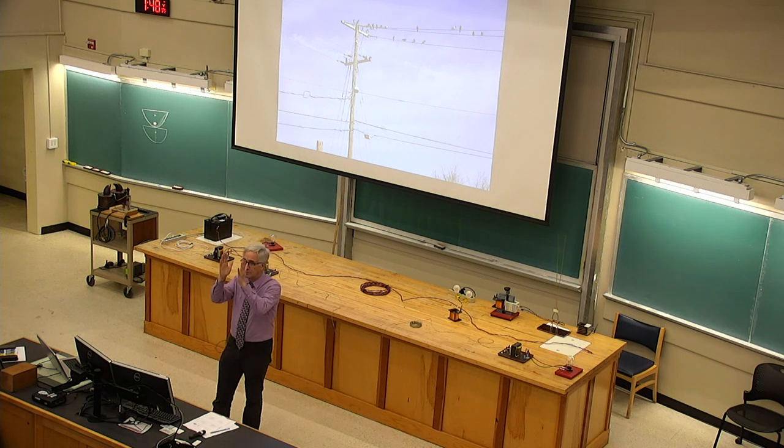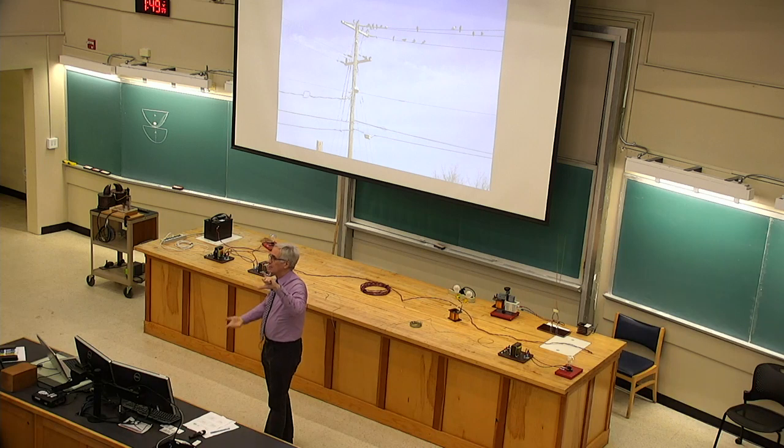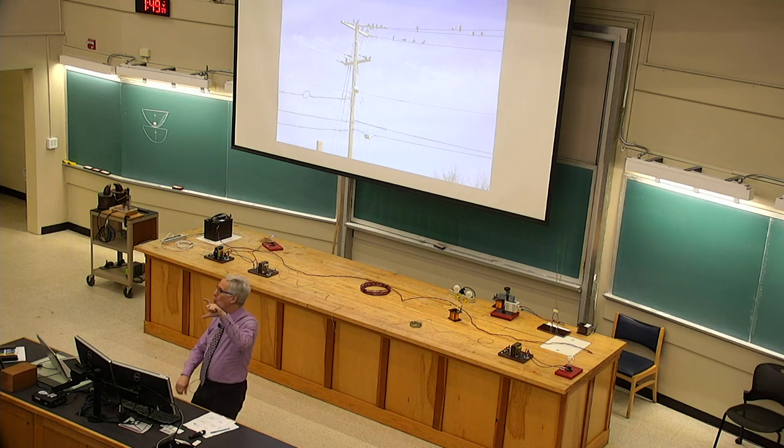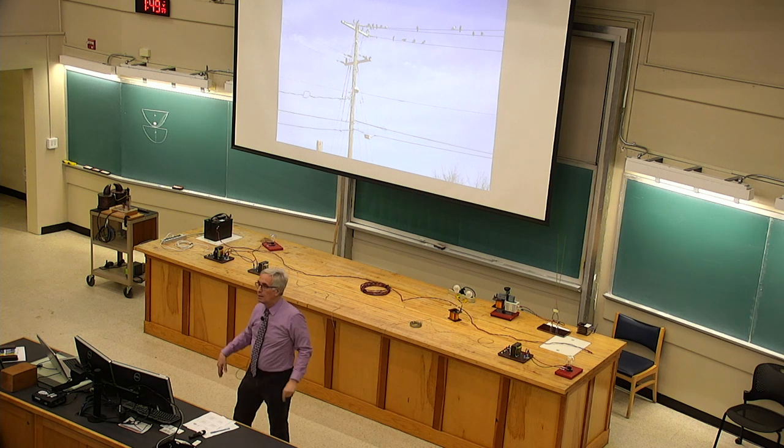The 2 slots. And the way they've got it arranged, standard electrical power distribution, the longer of the 2 slots, you've noticed that some electric plugs have a longer slot, two different length slots, and you can't plug the thing in the wrong way. The longer slot is what's called neutral. Its voltage is pretty nearly the voltage of the ground. It's supposed to be within 1 volt of the earth.